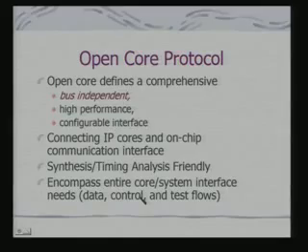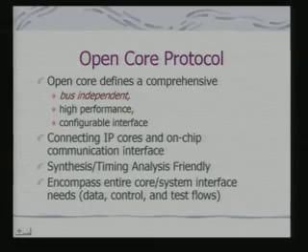The other trend which has developed related to bus for SOC is what is called open core protocol. The example that we have seen so far is that of a particular bus, proposed, used and popularized by the ARM processor manufacturers. It has definite transaction definitions and specific signal definitions, and when you are designing an SOC, you are picking up the modules compatible with this bus structure.